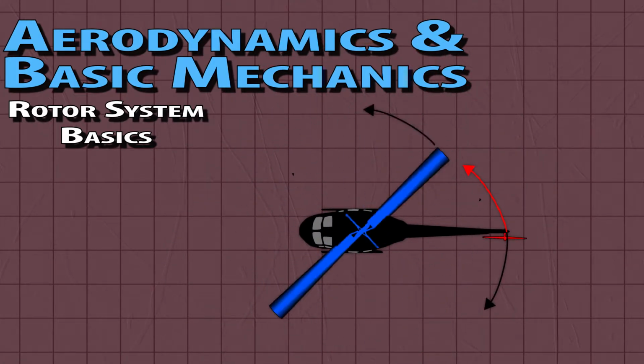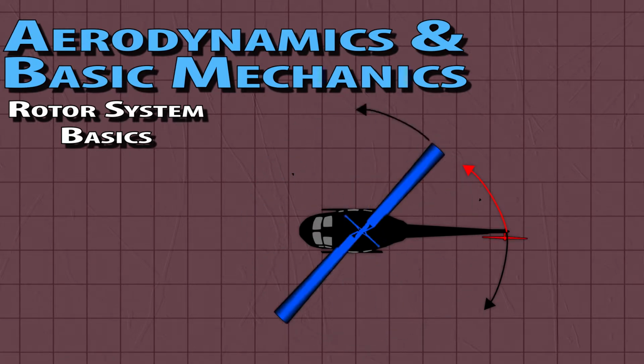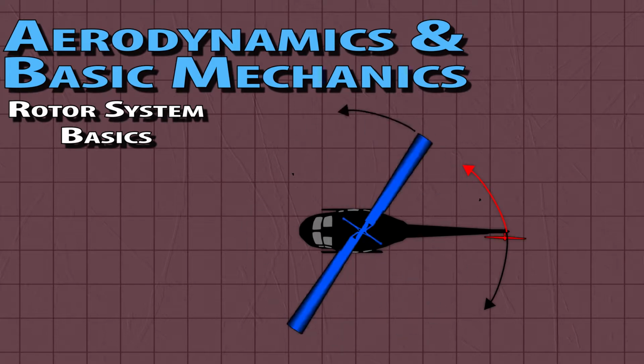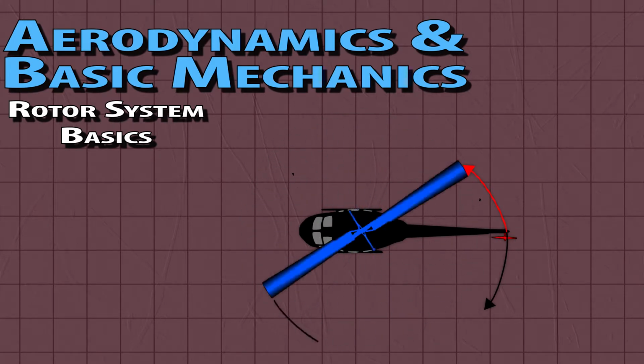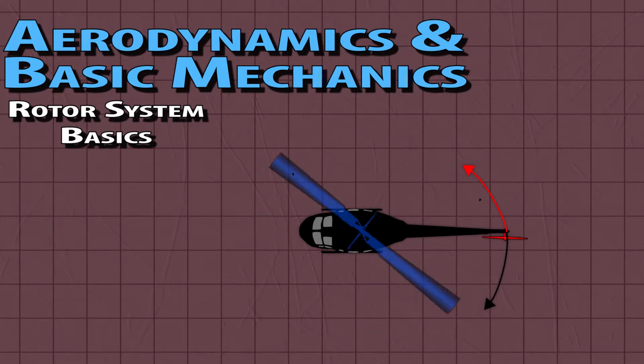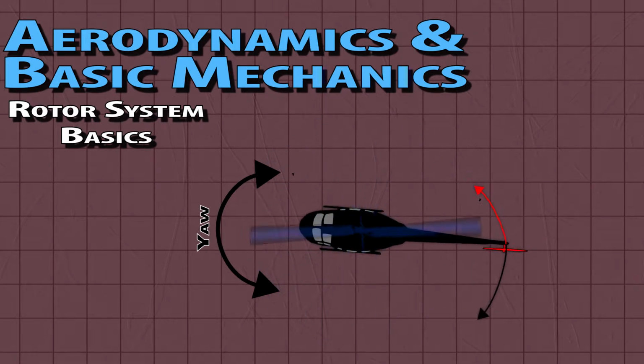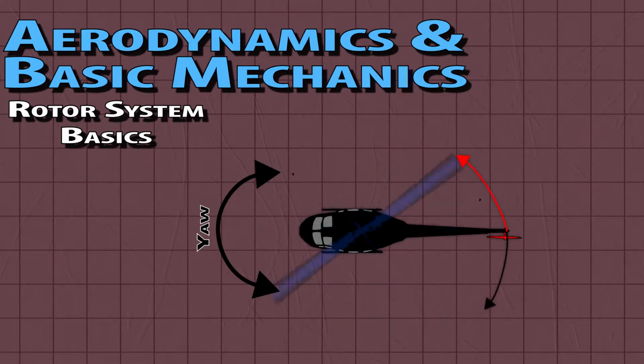The tail rotor works in the same way as the main rotor and is linked to the same drivetrain, but is smaller, perpendicular, and is geared to spin faster. Often it is set to one side, sometimes within the tail itself. Its purpose is to give yaw control. If it matches the torque of the main rotor, you will maintain heading. You can increase or decrease its effect to yaw either way.